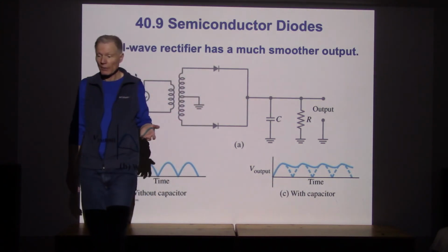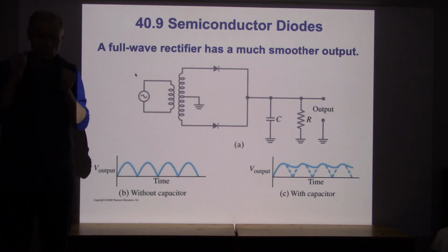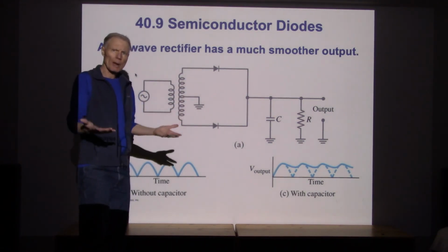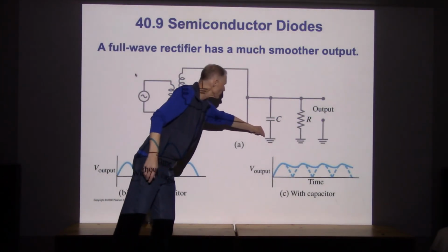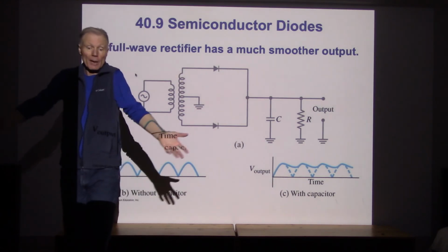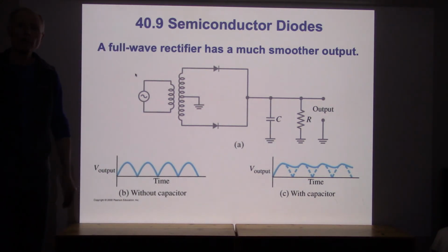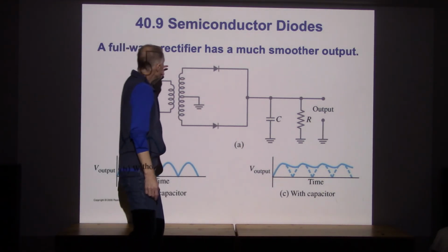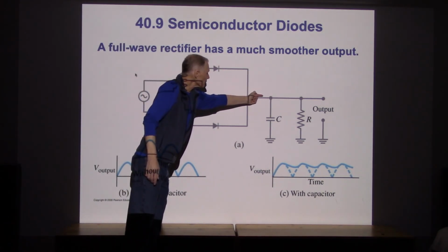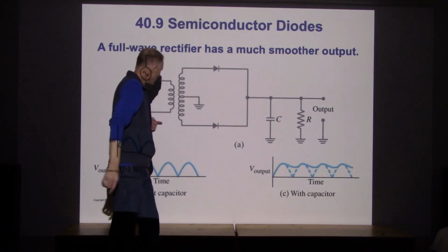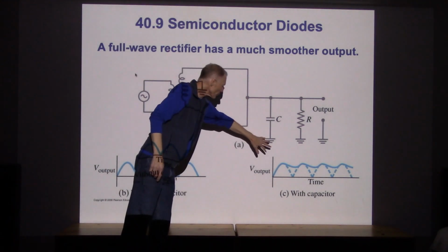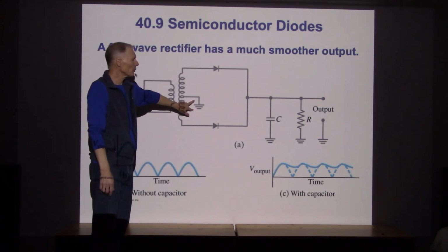Or it could also be that there's just some copper, big pieces of copper pounded into the ground, and it literally is a ground, meaning that this electrical connection between these two is to be carried out by the ground, by the earth. The rest of the conduction will travel through the earth itself. All right, so when the current's going this way, the circuit's completed through here, and then when the current reverses, the current goes this way, and the current is completed through here also.